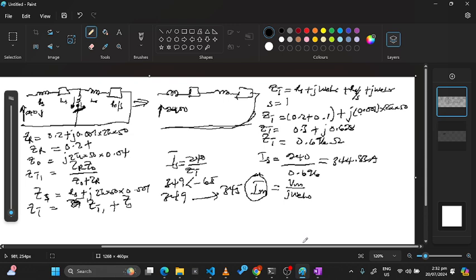Therefore, because Lo is a constant, this Vm and the ω_e should change in the same proportion, such that if I increase Vm by 2, so the new value of Vm is equal to 2Vm, then the frequency or this speed over here should now be j2ω_e Lo, so that at all times the proportion will be the same, or they will increase in the same ratio. Is that okay? It's a principle we are now going to look at, but the question is here, so we need to look at it.